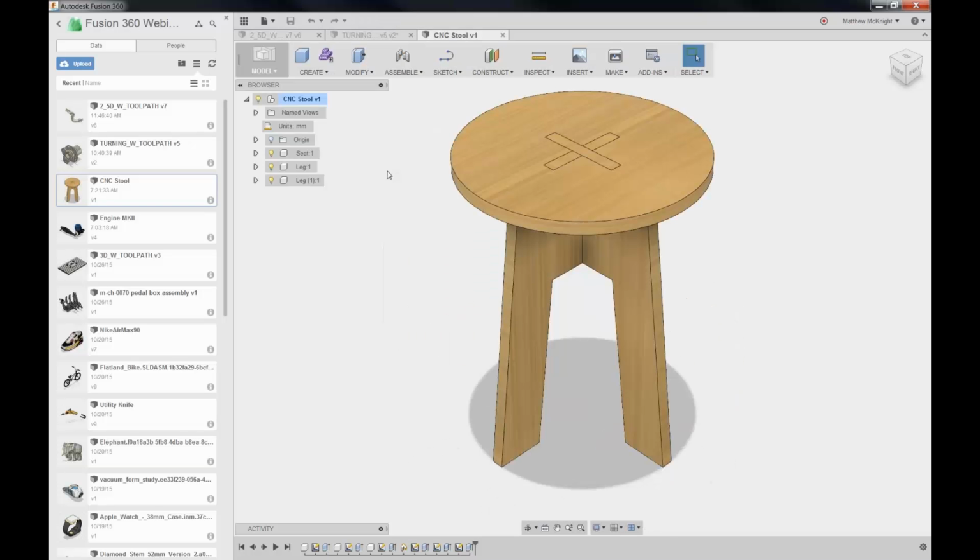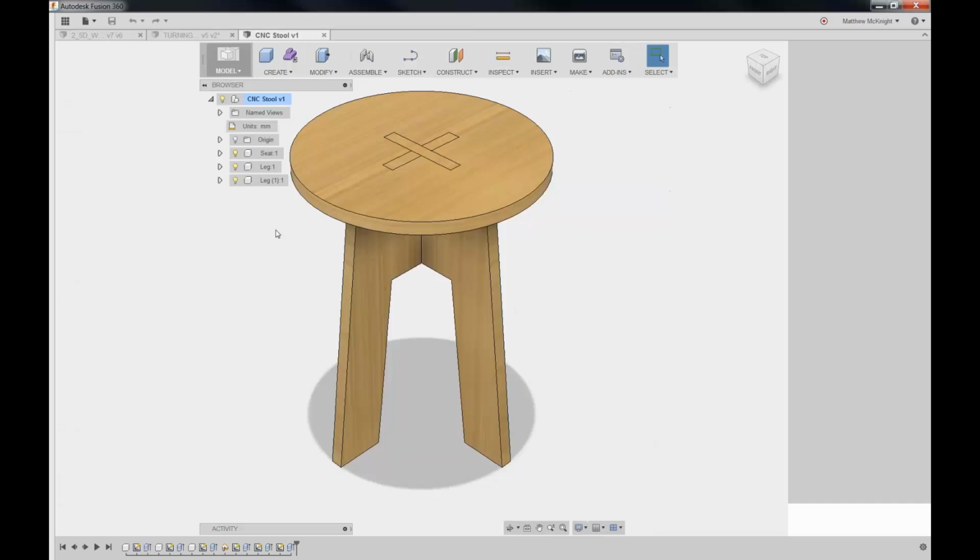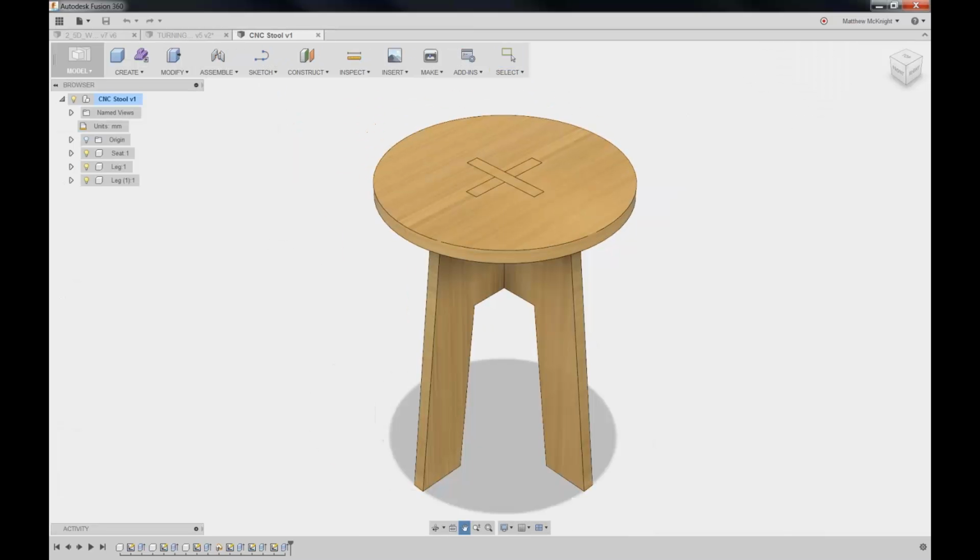So here's our part. Fusion 360 doesn't have nesting software. It doesn't have any nesting capabilities at the moment. If you're looking for nesting capabilities, there is a product called TrueNest that is an Autodesk product. Works with a whole range of products, including Inventor, and it will do effectively almost anything that you need it to do when it comes to water jet, laser, plasma cutting, and even turret punch fold machines as well, including nesting and programming all the code, and it's completely automated.